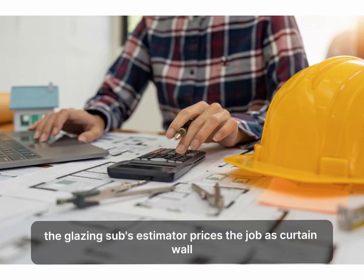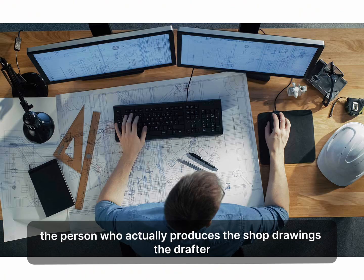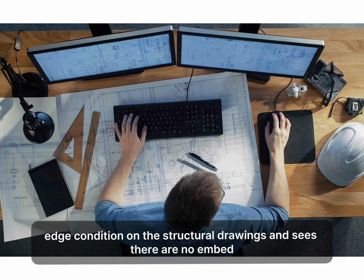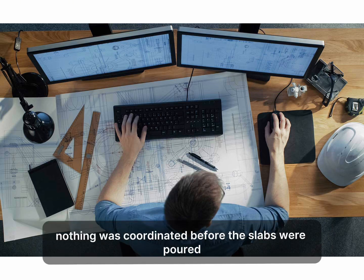Here's how the issue actually unfolds. The glazing sub's estimator prices the job as curtain wall. That's what the spec says. That's what he bids. But when the project goes to their drafter, the person who actually produces the shop drawings, the drafter looks at the slab edge condition on the structural drawings and sees there are no embed plates, no cast-in sleeves. Nothing was coordinated before the slabs were poured.